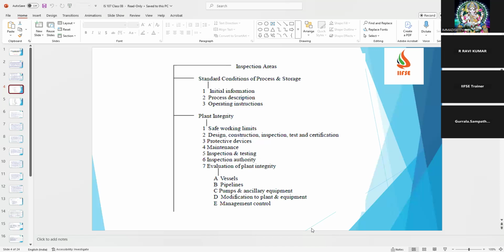So unfortunately, one of the engineers or chemists used nitrogen for the air hood, the continuous air supply. He died on the spot, because it is colorless and odorless. You are not able to detect what you are breathing. So it is very important, especially for pipelines, that you should have proper color coding, color coding awareness training, as well as labeling also.